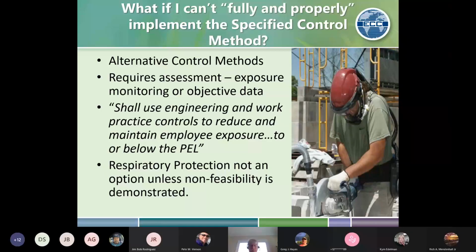The smaller particles that the cyclone doesn't remove stay in the airstream, and after circling around the cyclone several times, get sucked up into the filter. What lands on that filter is your sample of respirable dust, and that's what we have to have analyzed.